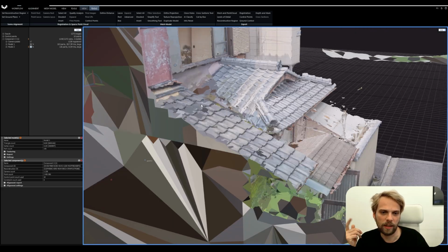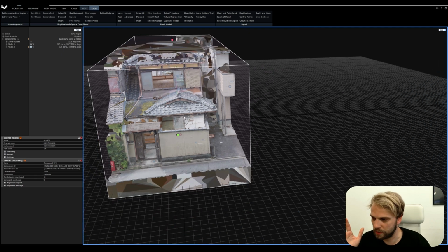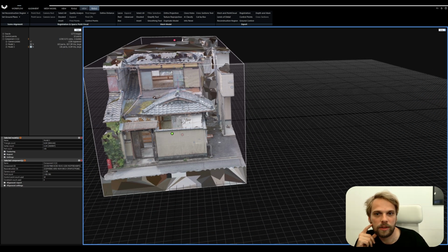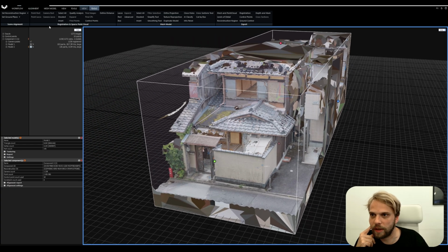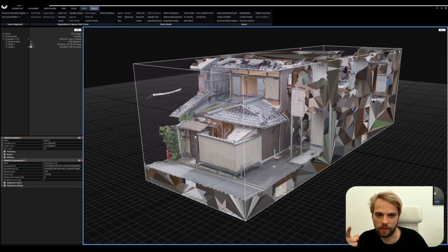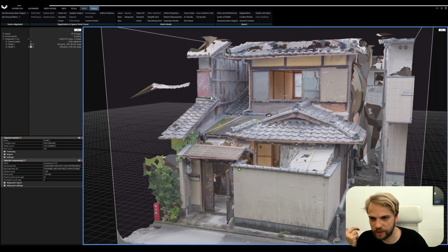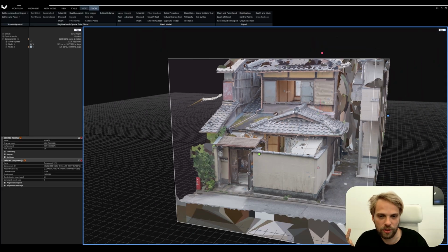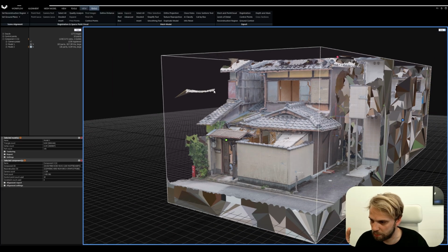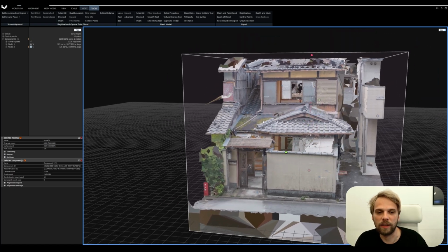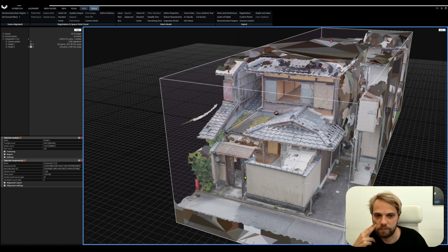Okay, besides that, now what we need to do is clean this up, import it into Rhino, and that's going to be it for the video. The way I clean this up is basically in three parts. Part number one is getting rid of all of the floaters, as I call them. So stuff like this, meshes that are separate from the rest of the geometry, just these floating bits and pieces that don't give any additional information to our main mesh.